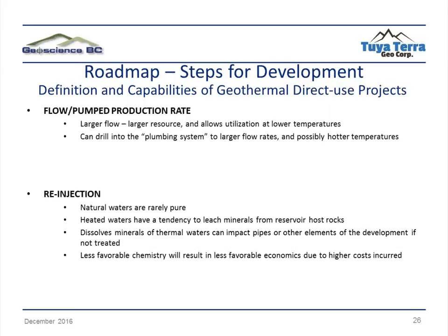So again, it's all about temperature and flow rate. As the calculations on the amount of energy that you can extract show, we need both the temperature of the fluid coming up, and how much of that energy in the fluid we are going to use. It's very important to understand that, because that really is how we're going to make our development. What can we do with that hot water? How much of it do we have? How quickly can we get it to the surface? And I've already mentioned reinjection.